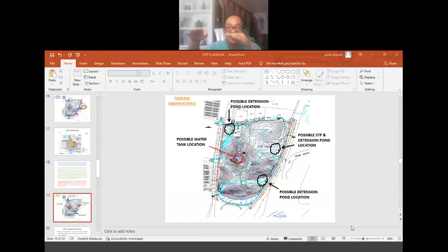If the water is below the level of the weir, then the water is stored. When there is heavy rain, the water will start to rise up. Heavier still, the water will start to overflow the weir. And when it overflows the weir, then it goes out as discharge. So this is one way to control flash flooding.